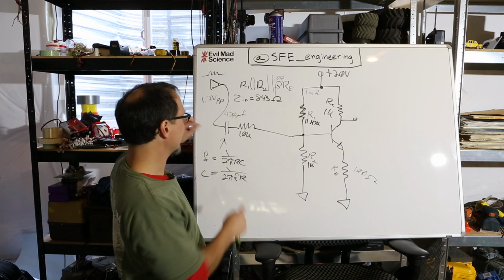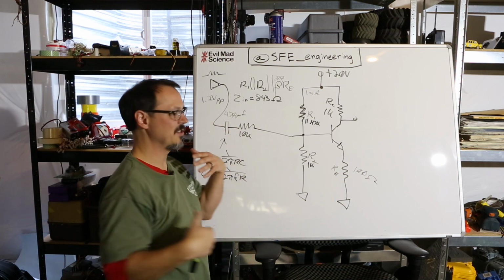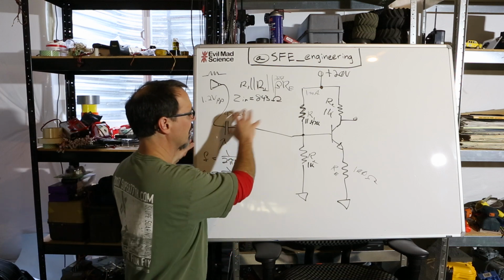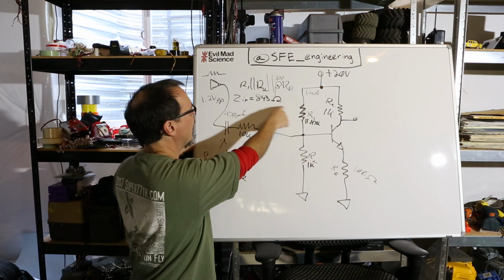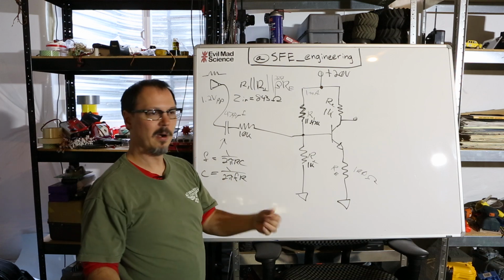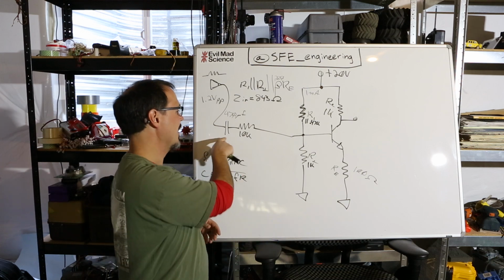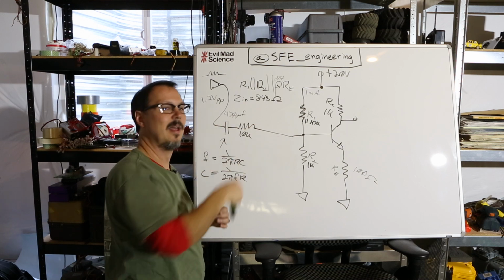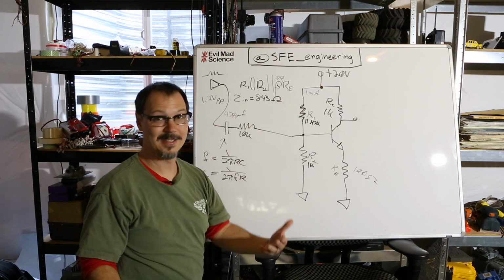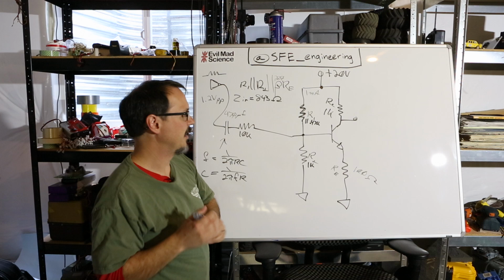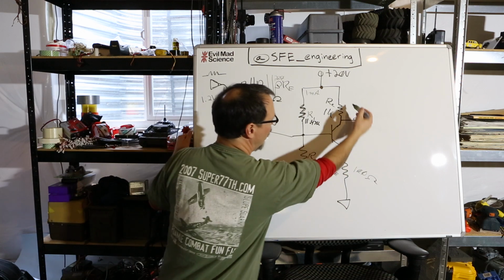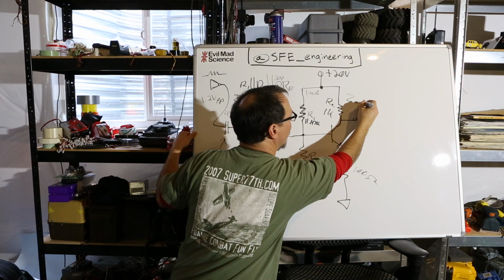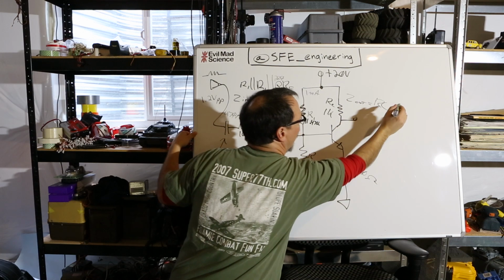So the point of that is this guy has to be as invisible as possible over the frequency of interest, meaning every other resistance, this 10K, that 843, are much bigger, and that's where the voltage is dropping, not across that. Also, this thing can have an impact on the phase of the signal. So the bigger that value is, the less the phase is going to impact it as well. Now, getting the signal out, your output impedance of this guy is effectively RC. Z out equals RC.